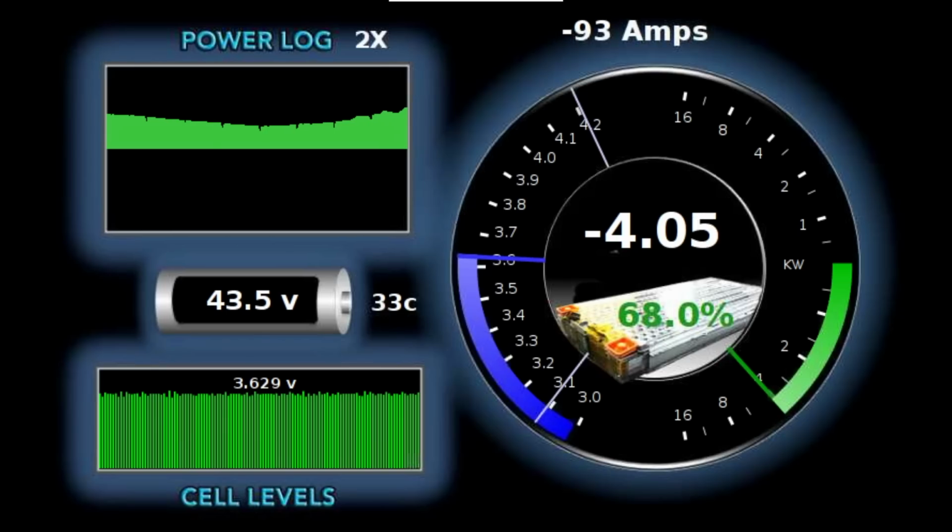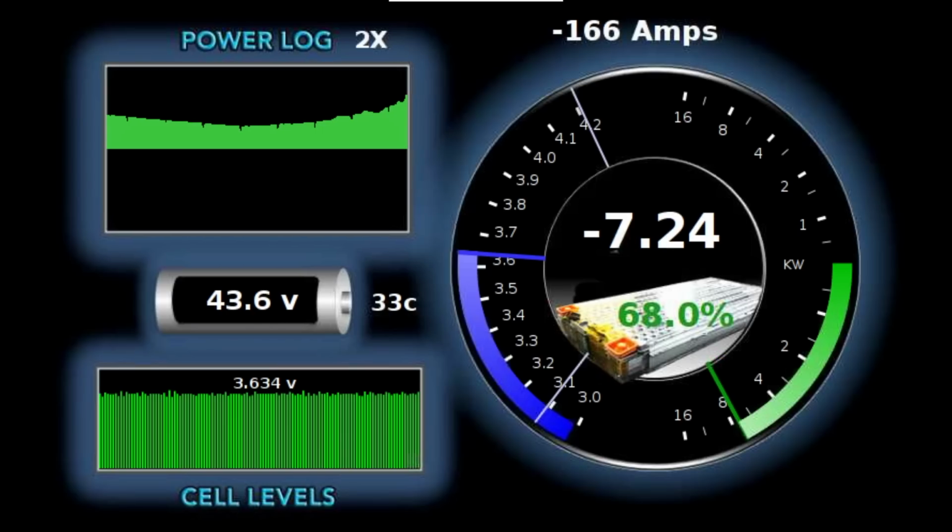That's going to be a configurable item that you can set to what you want, but I would really look at 10 seconds or 20 seconds to be a good time to do it. It depends on what definition you want to see, but at 1 second you get every little change logged here. But that's largely for test purposes. In normal operation, I would have that set to 10 seconds probably, or even 20.